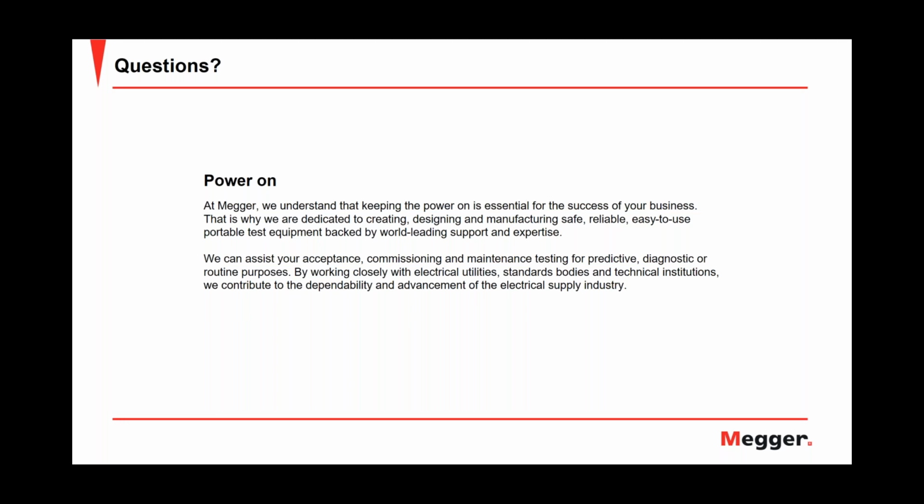And also the time is much longer. I think in the example that Robert used, a 25 kV cable with 19.9 phase to ground voltage, when you have a fault in the cable, you only have an air gap of about 245 mils, the thickness of a 25 kV cable. You can roughly say the breakdown of the air gap is only 1 kV per 40 thousandths, 1 kV per millimeter. So you have maybe about 6 or 8 kV breakdown voltage, right? The fault locating voltage is purely a function of the thickness or size of the air gap. It has nothing to do with the voltage rating of the cable. That's very important to understand.